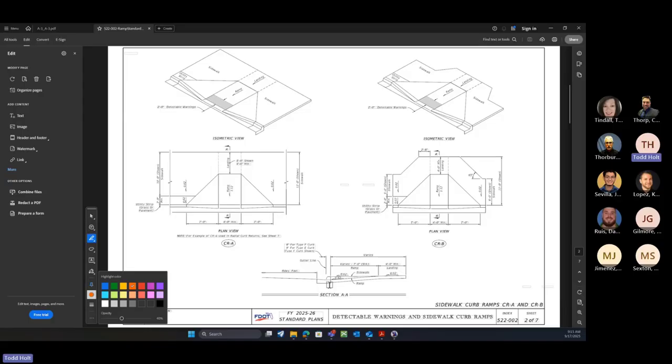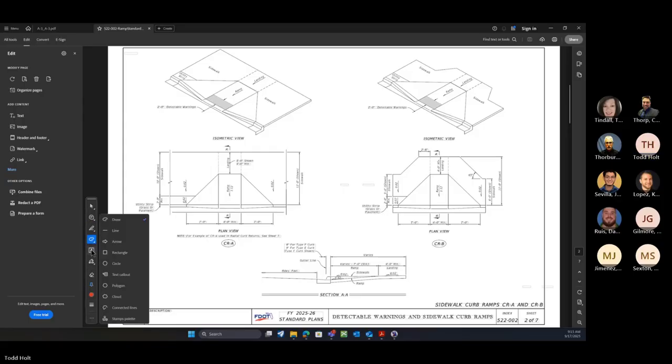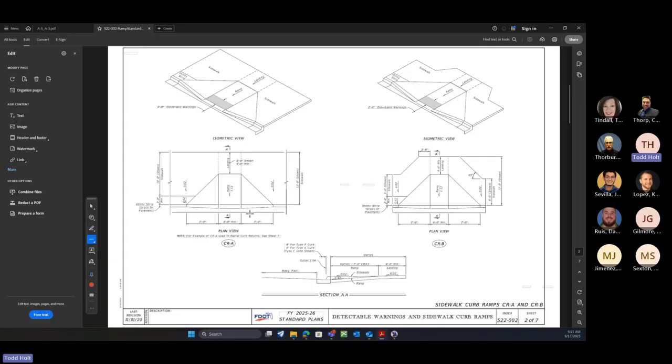Depending on what we have, if the gutter line or the curb is built into this, or if it's just going to be from the sidewalk back. So if we want to place this, maybe we have curb built into there. Maybe the edge of pavement is going to be a reference, our flow line, and the back top of curb to build that. So we may have three references. We might just need the curb, the flow line, maybe the curb back. But that's one thing we want to figure out: how do we want to place that?